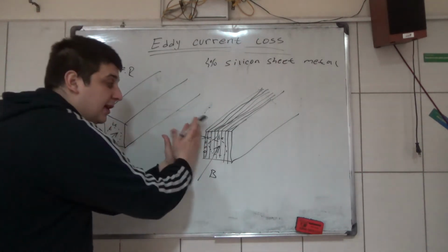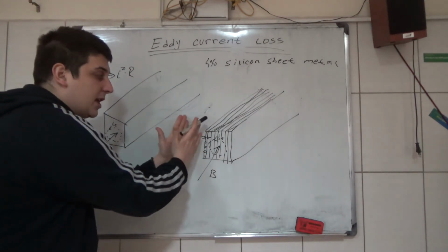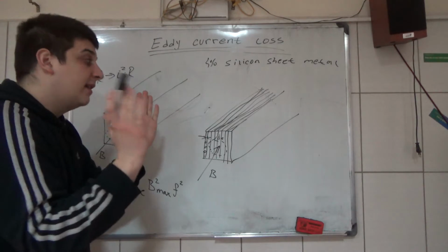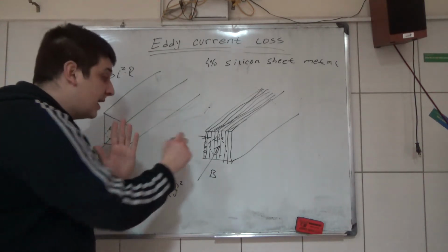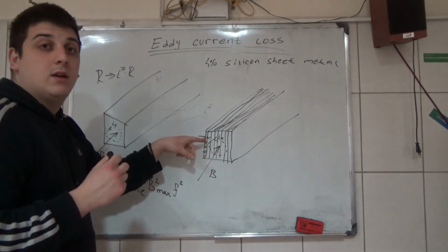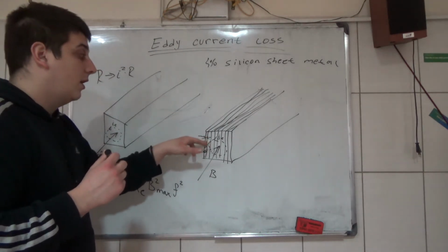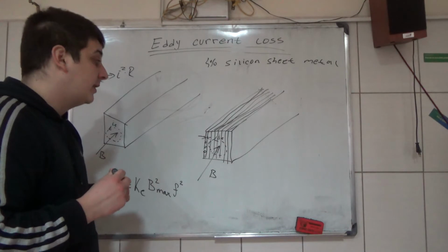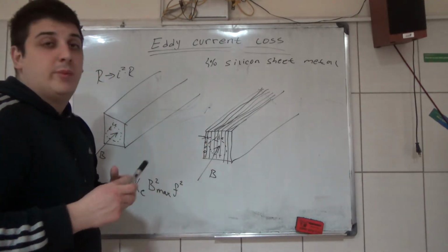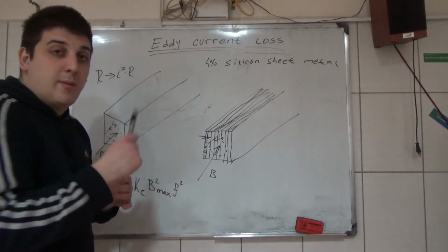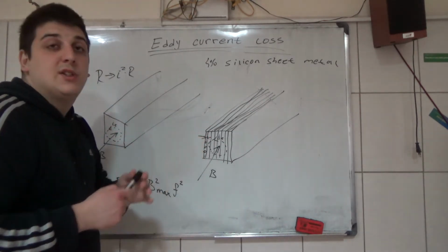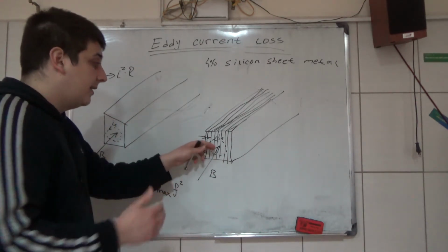So you make these magnetic laminations thinner and thinner. You put an isolating material that is much thinner than the laminating magnetic material, and then there will be a smaller amount of electrons that circle, so smaller currents.